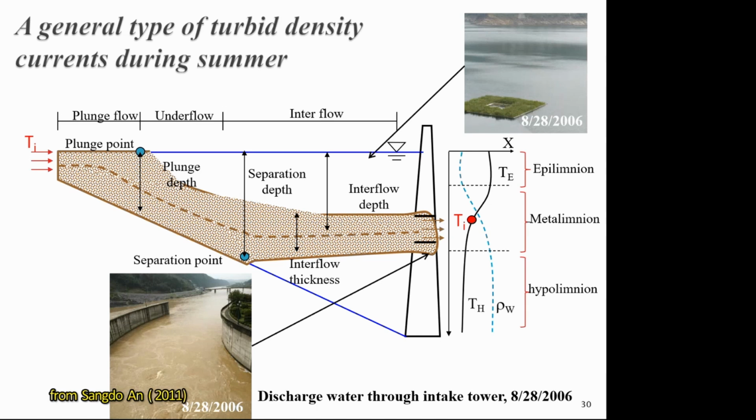Make sense? And if your concentration goes higher than, let's say, 2,500, that's my rule of thumb now, it is going to go down and you're going to get a sinking density current that's going to go as the underflow. The problem we have at this point is with the water intake. You design this and say, well, all the density current is going to go down here. We get the mud here, we get clear water, we extract clear water, and we release that,